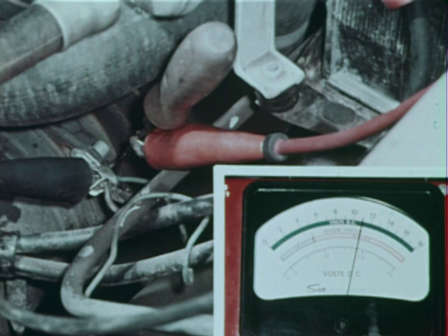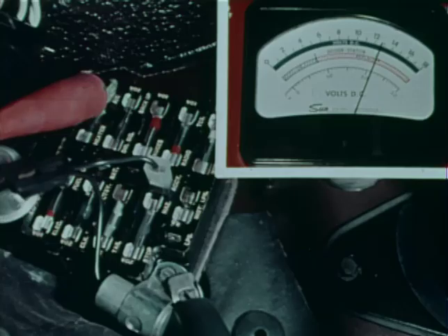So next, test for proper voltage across the compressor clutch coil. With the system operating on AC and high blower speed, the voltage across the clutch should be at least 11.5 volts. If this voltage is present and the clutch is chattering or only partially engaged, then the clutch or clutch coil is defective. In this case, the voltage reads below 11.5 volts.